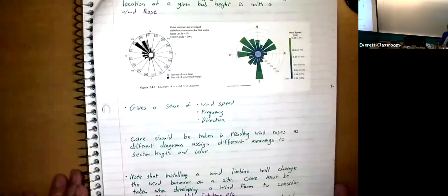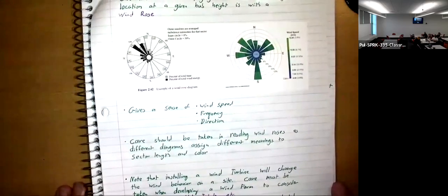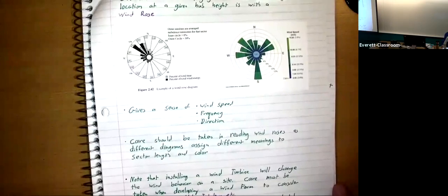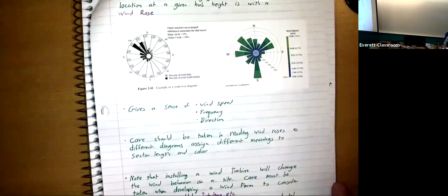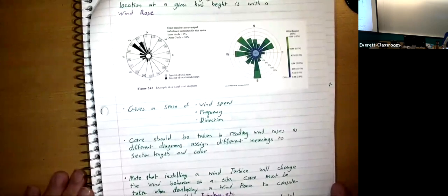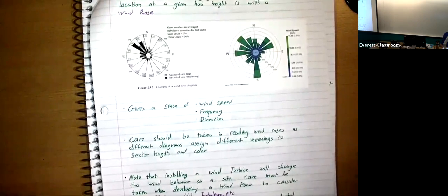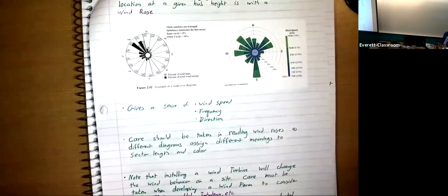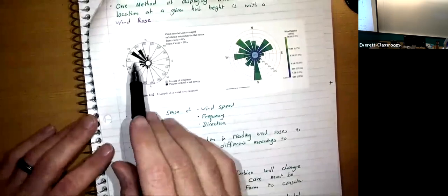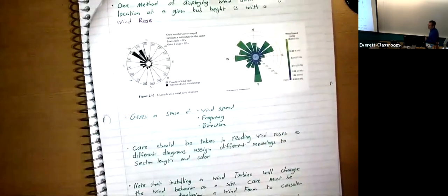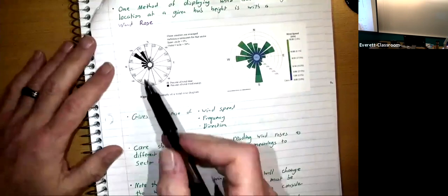So when you're designing a wind farm, you need to know, am I going to put a wind turbine in the wake of another wind turbine? The thing is winds change direction. So you can't put a wind turbine anywhere without it somehow being in the wake of another wind turbine at some point, okay? So just like we look at the probability of the wind speed being a particular speed over the course of the month, we also need to know the probability that the wind is going to be coming from one direction or another at a particular time of the month. So a windrose gives you this information.